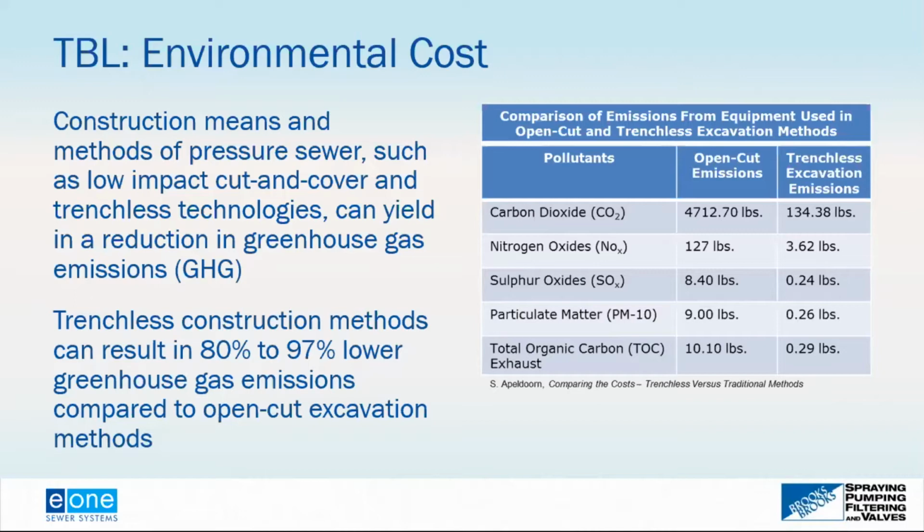And what they found was that construction that uses trenchless technologies can result in an 80 to 97% lower greenhouse gas emissions compared to an open cut excavation. So when we look at gravity sewer versus low pressure sewer systems, it's not like low pressure sewer systems in and of itself provides a more favorable environmental cost, but the means and methods in which we install that system provides a much more favorable environmental cost as it relates to the production of greenhouse gases.